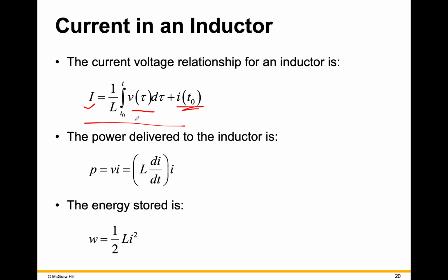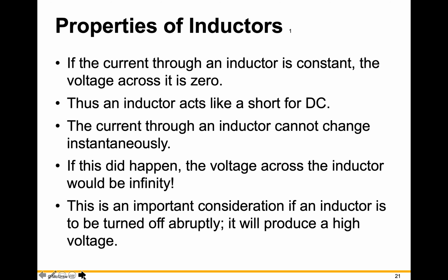Okay, we do a similar thing with power that we did with capacitance. Power is V times I. V is L di/dt, so we substitute that, and then to get the stored energy, we integrate the power, and we get 1/2 L i squared.